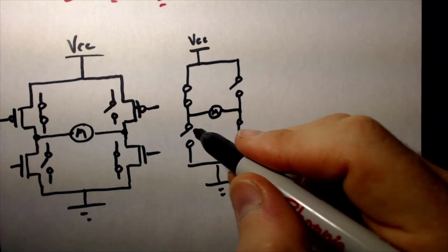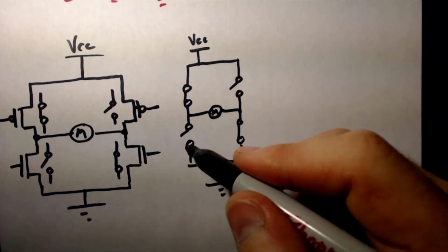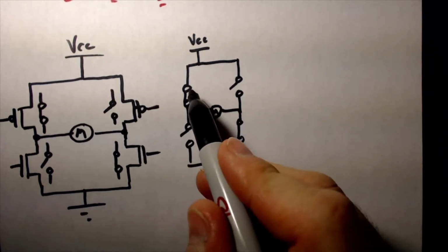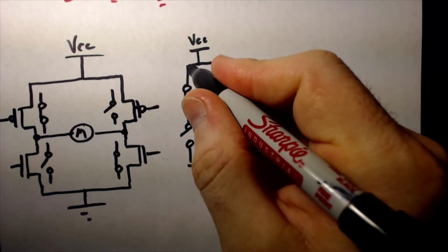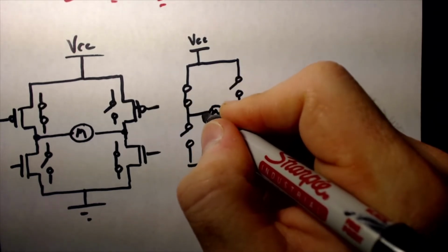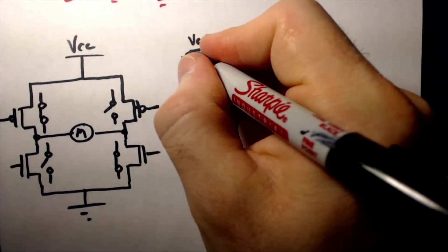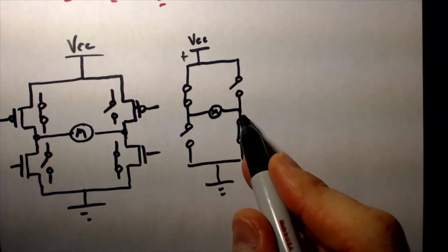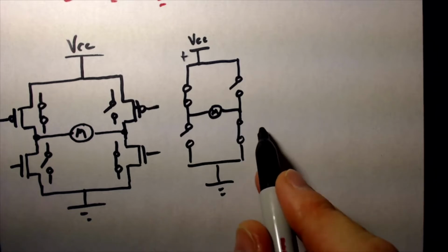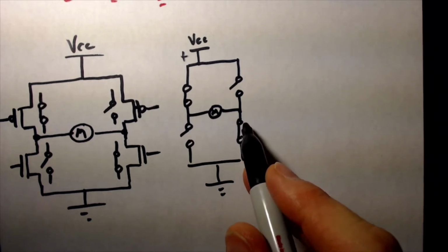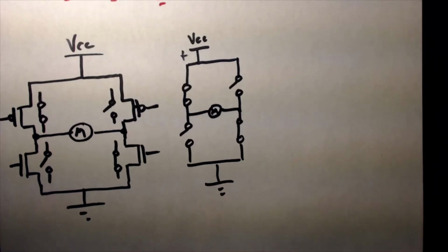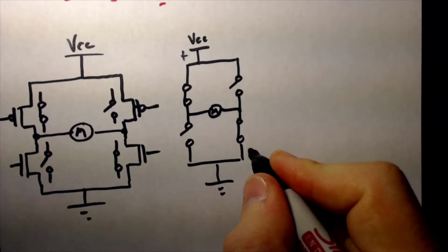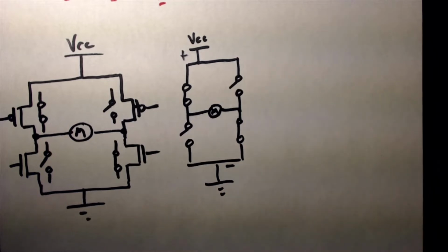Now just look at these switches, these MOSFETs. Notice my P channel on the upper left is now closed, providing me a pathway that connects this side of the motor to our positive voltage. And I have a corresponding N channel down here that is acting as though it's closed, pulling this side of the motor down to ground, giving me minus over here.